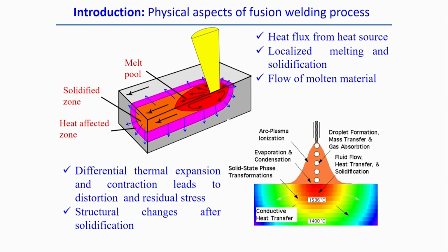That molten droplet transfer from the consumable electrode actually influences the weld pool, in the sense that there is a continuous adding of mass to the solution domain, and that influences the material flow within the small weld pool. And of course, with the advancement of the consumable electrode, solidification also happens, and heat is lost due to convection and radiation from the surface.